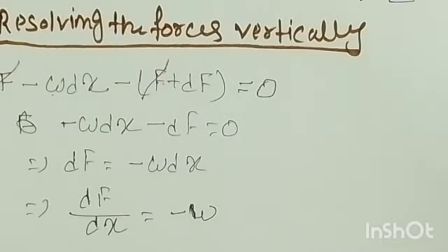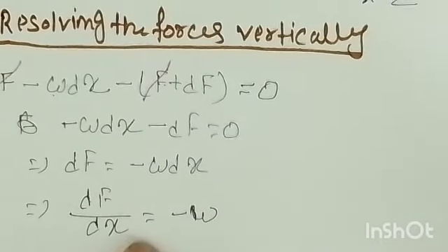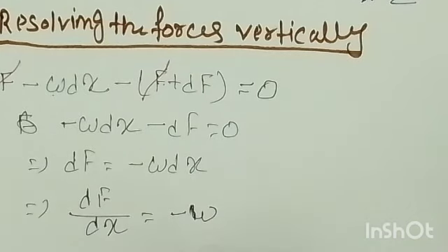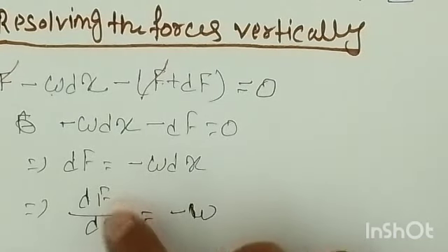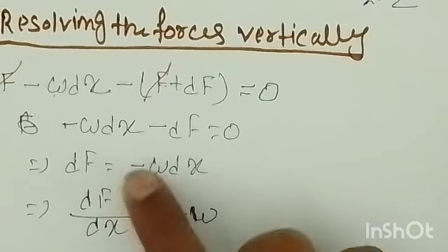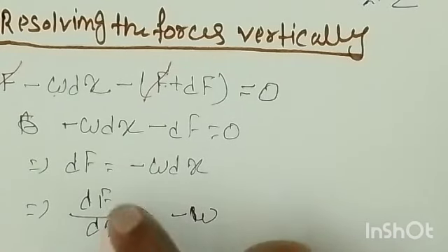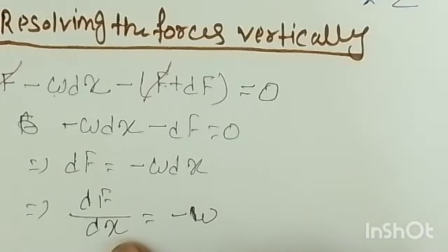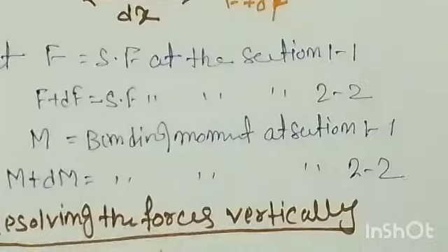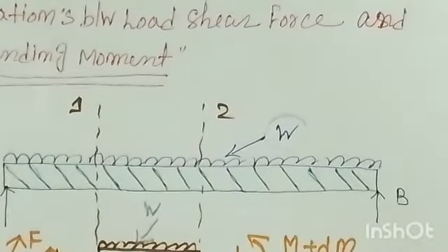What is the above equation telling? The equation tells that the rate of change of shear force is equal to the rate of loading, right? Rate of change of shear force means, F is the shear force, and when you differentiate the shear force with respect to x, that is with respect to position, you will get the rate of loading. Rate of loading is nothing but the UDL, right? Now, so now you can say that here we'll see, wait.